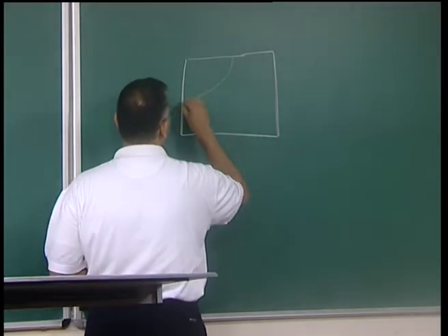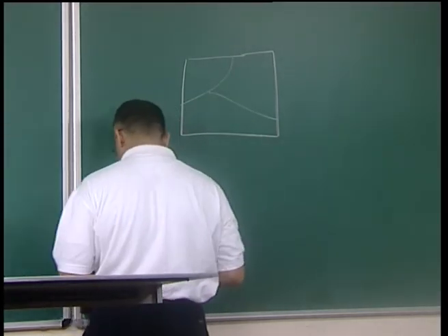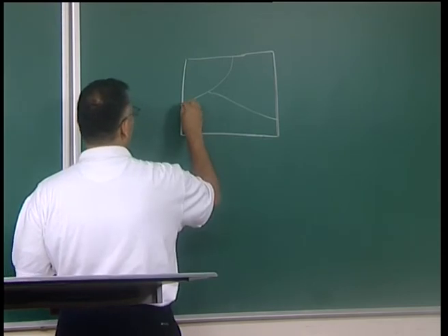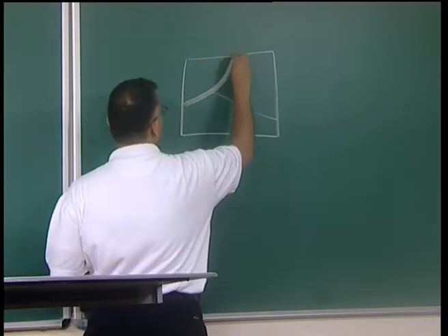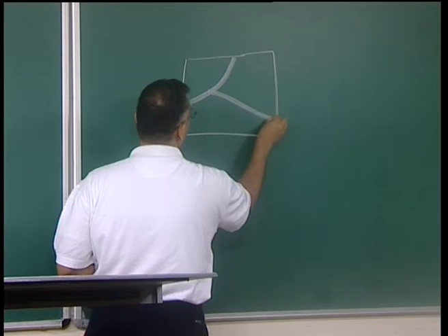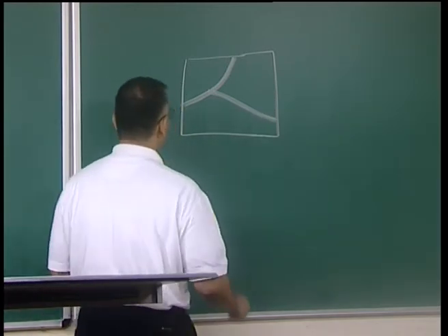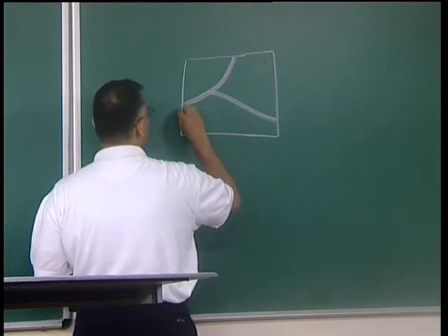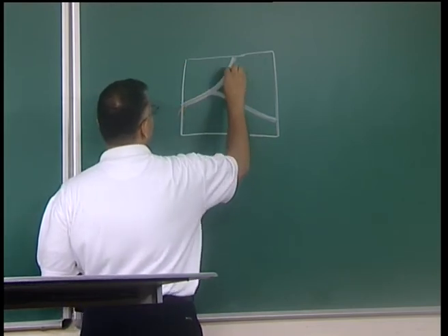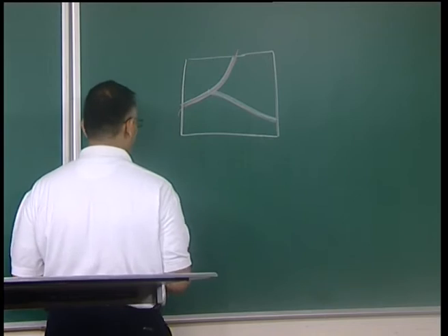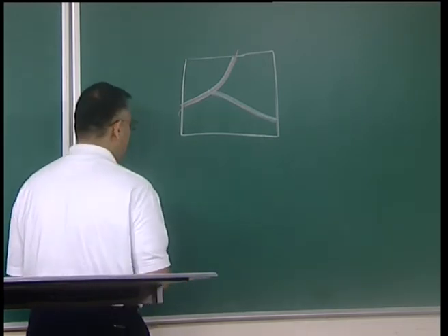What might happen is that, so you have your polycrystalline grain boundary. So, what might happen is that when you slowly cool from above, you will produce a continuous network of cementite along the grain boundaries. Now, the cementite is a brittle phase, a hard phase, therefore, continuous cracks can propagate along these paths, and therefore, the material may fail in intergranular fashion.